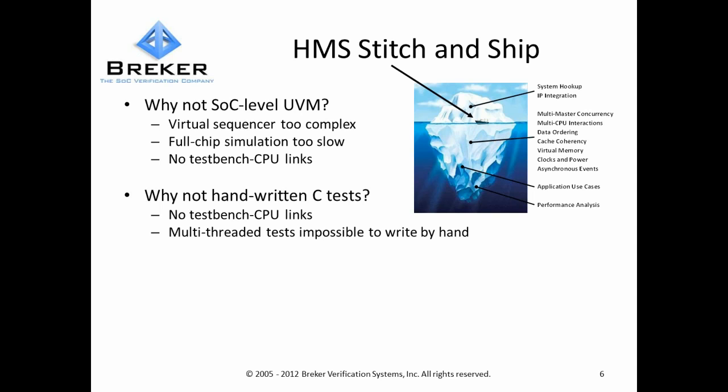Why not just write a test by hand? Well, frankly, we simply don't have enough time to write a number of tests that we need. And it is almost impossible to emulate multi-threaded operations in a test case by hand. Nothing's impossible. Enough time, enough people, you can do anything. But for a human being to sit down and write a multi-threaded test case that runs on bare metal without an OS and correctly interacts with I/O is very, very hard.